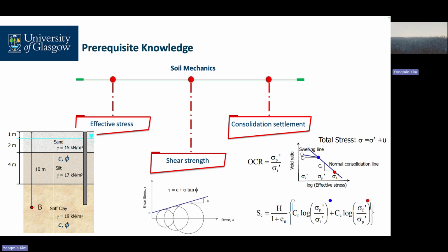plus 4 meters times 17, again confining our pile. From here to here, I don't know. We are supposed to determine its remaining length times 19. These combined pressures improve our bearing capacity. That's why effective stress is needed to calculate our bearing capacity.